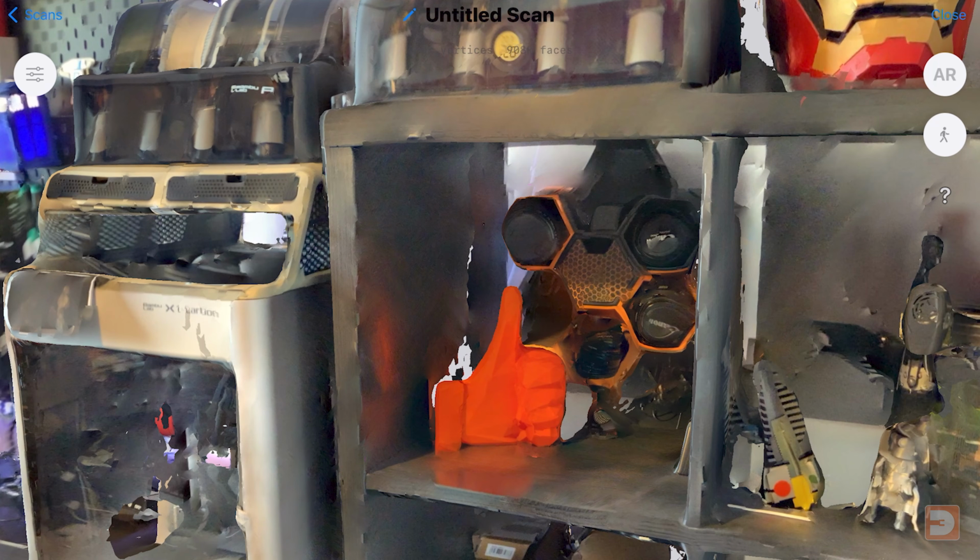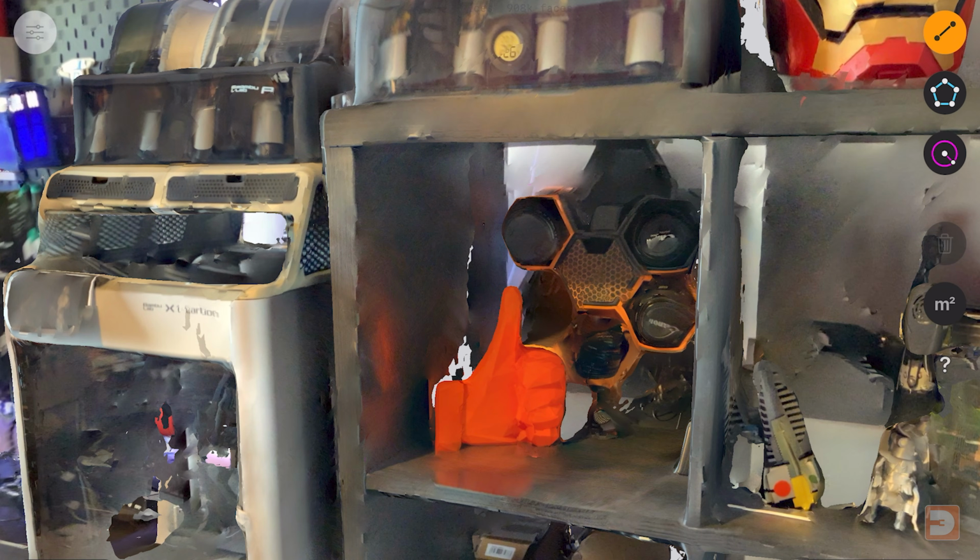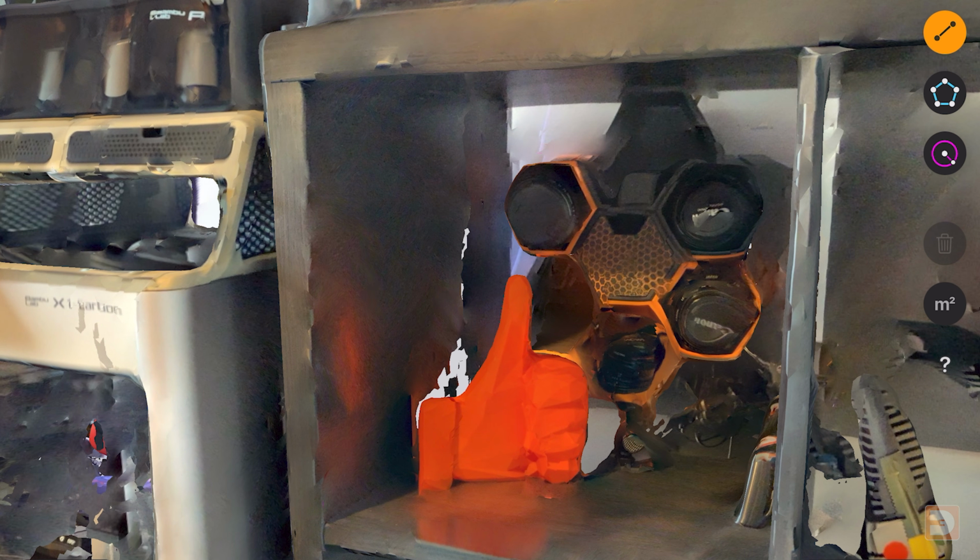But it's also a really useful tool for 3D scanning, not just being fast, but also due to the way it works, it can scan things with relative dimensional accuracy. So if I was to scan these shelves right here, they've got roughly 33.5 centimeter gap between each shelf. If I was then to measure the space between the shelves in the scan, it would automatically show around 33.5 centimeters without me having to have manually scaled up or down the model to be the right size.